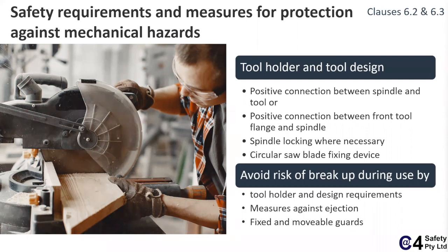Yes, I did a training course once, Mel, where a guy was using an angle grinder, but he put the wrong size wheel on. The hole in the wheel was too big, and it shattered. He was wearing a welding mask at the time, and it penetrated the mask. So this issue of spindle control and locking is incredibly important.